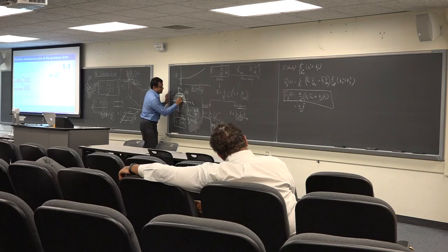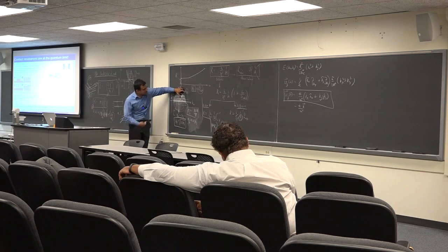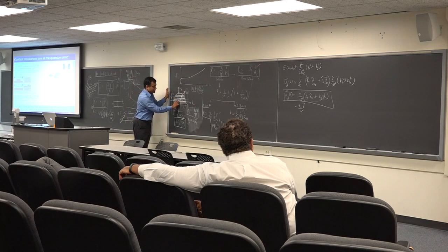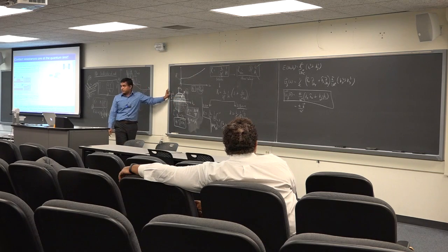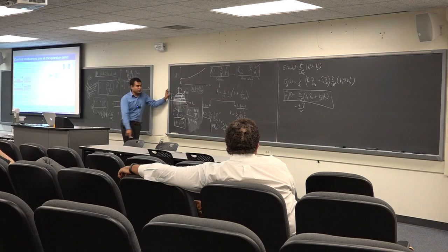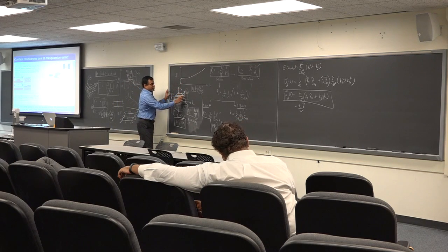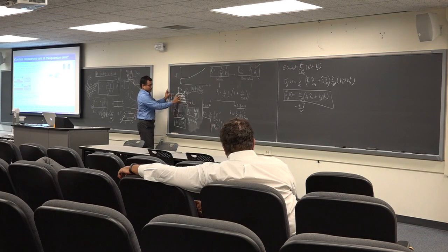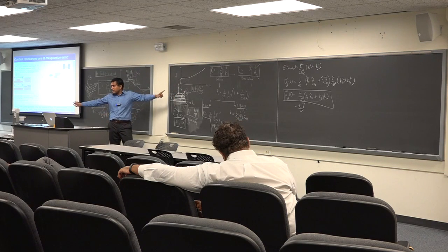So essentially, the velocity is radially going outwards, and the magnitude of the momentum h bar k is proportional to how far you are from the origin, right? If kx and ky are 0, you're sitting here, that electron is not going anywhere. Its group velocity is 0. Then you go here, it's going that way. If you go here, well, it's radially outwards, and it's moving faster, but going that way. I have an electron here that's going very fast, actually the fastest among everything inside, but it's going along the y direction, not from the source to drain, but laterally.